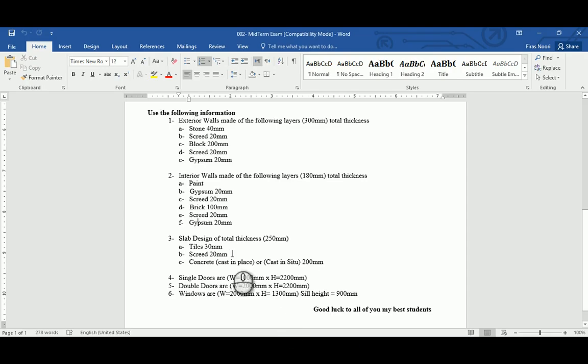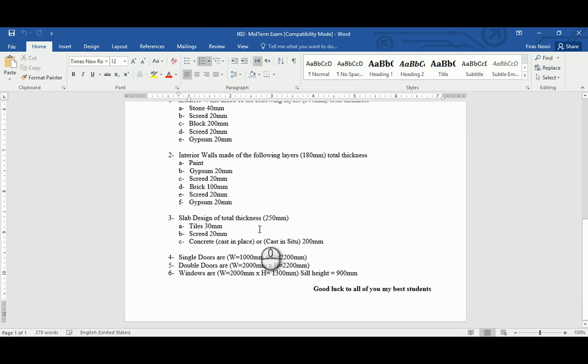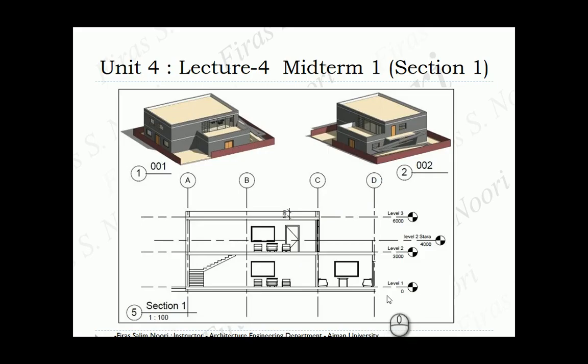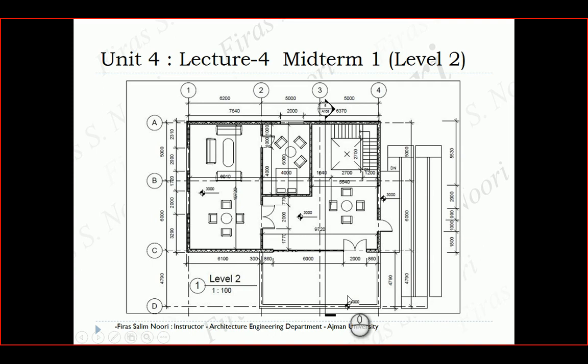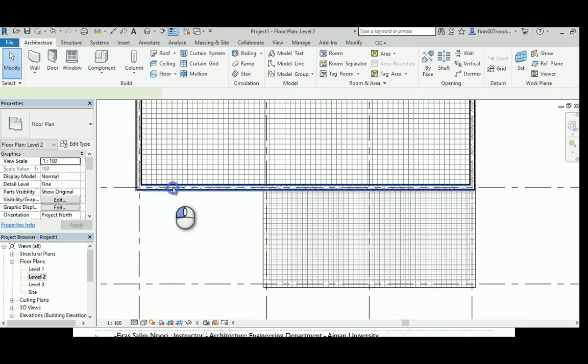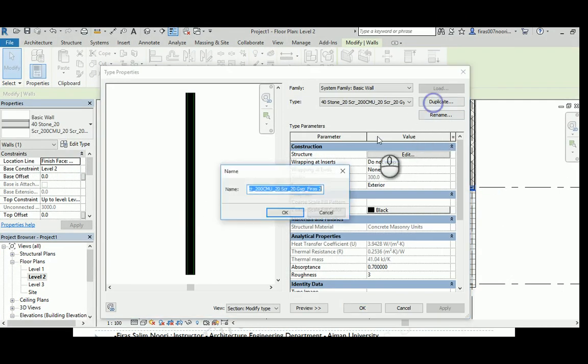So I didn't specify anything in the question for the parapet material, and in the PowerPoint, if you look, it's just a specified thick material without giving the dimension. So that's your shot, guys. You can just go ahead, for example, and select this guy, maybe duplicate it as we suggested and make it 2, and instead of gypsum, you can just go ahead and cancel it. Keep just the 20 secured, or make it CMU face from the other side.